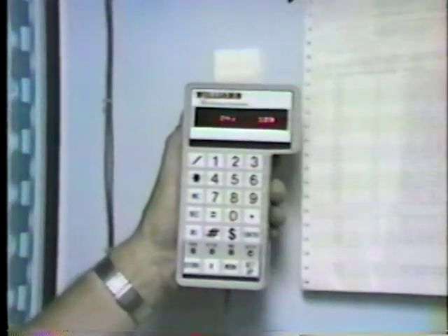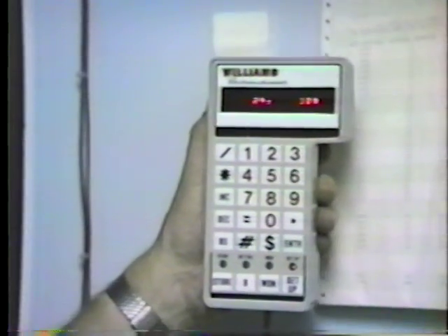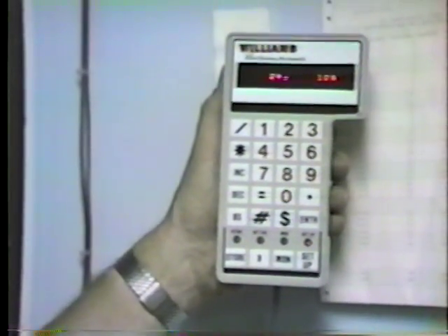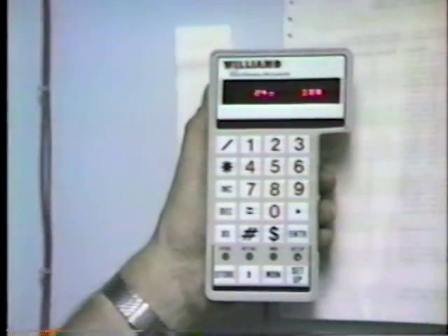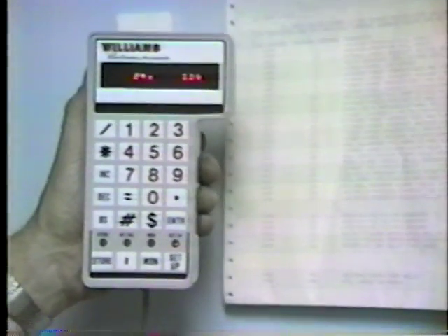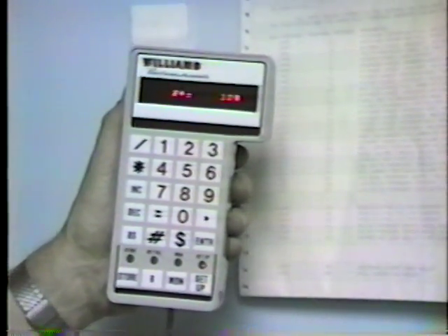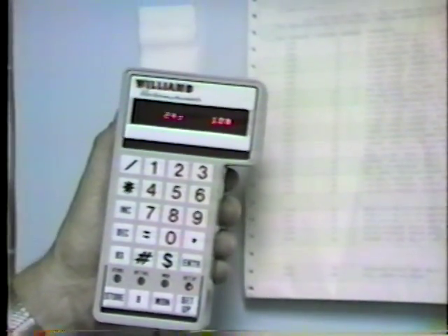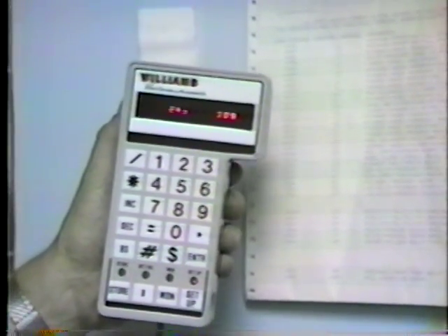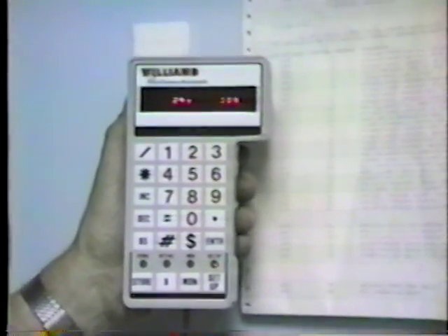24 is the milliamps too high alarm timeout. We had the setting for the milliamps up above. This is the time that we will allow the milliamps to be above that line before we declare the wear alarm. In either case, we're talking about a non-fatal alarm. It's a warning. So you've got 10 minutes, yes, and this is a debounce type thing. It has to be really proven that it's over. All right.